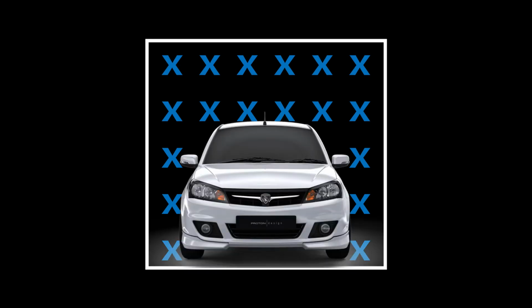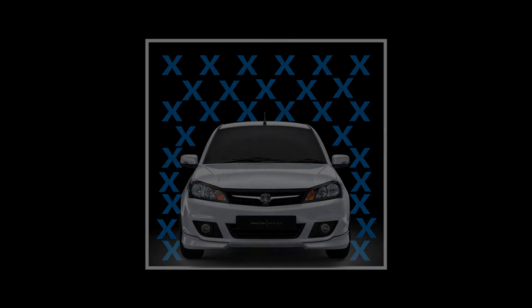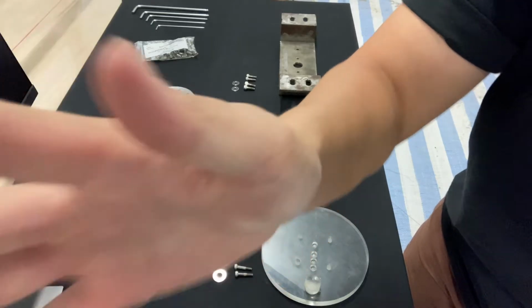Another thing to consider is something called blockage ratio. Let's say this is the cross-section of a wind tunnel. With nothing inside, the airflow is pretty uniform. Now, if you were to put a car in the middle of the tunnel, all that flow that's being blocked needs to get through one way or another because of conservation of mass. So, for the example of this car, you end up with a different airflow than what you would get on the open road because the physical existence of the walls in the tunnel affects the flow. To mitigate this problem, a blockage ratio of less than 10% is common practice. Now I'll show you what our test setup looks like.